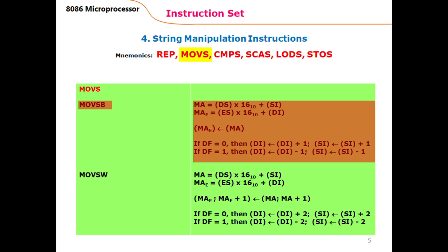The content from the data segment is taken, and it is left shifted by one hexadecimal digit, or that is equal to multiplying by 16 in the decimal system, or by left shifting 4 positions, 4 binary digits, or by introducing 4 zeros at the rightmost positions in the binary.